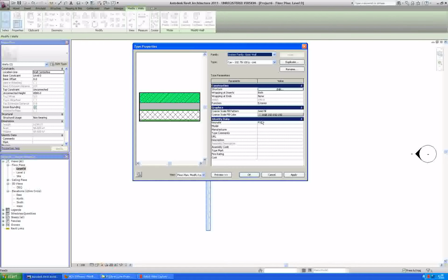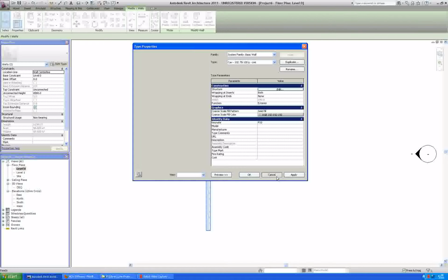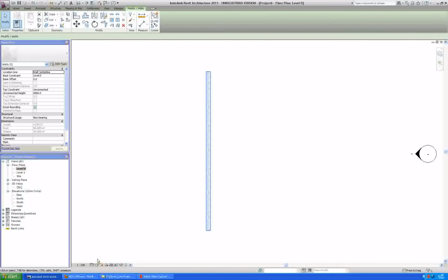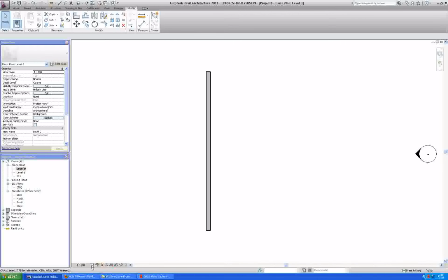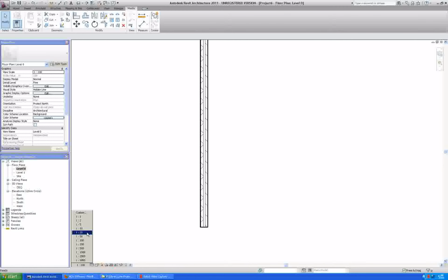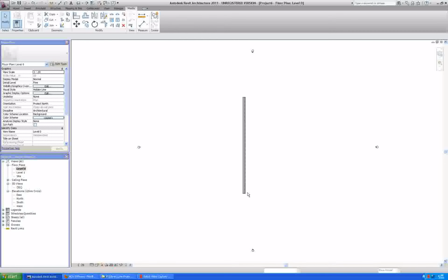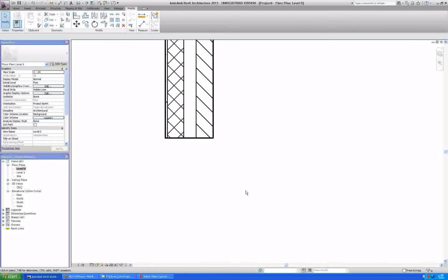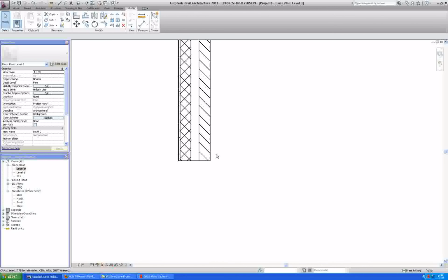Well, actually you can see in here the course fill, because that's another subject, but down here you have your detail view, which is what we have worked on, but you can also see the course where it just becomes a solid, which is probably what you want in 1 to 100. But in 1 to 20 it might be nicer to see our hatch and how it looks. And you can see it's scaled with the scale of the view, the hatch scaled down.